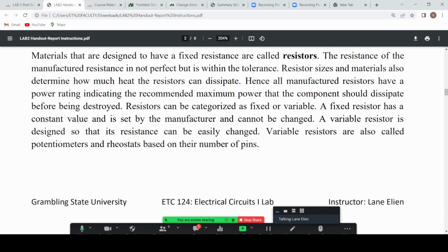That is why we have tolerance, so that we can have quality control. So when we manufacture a resistor, the resistance is accurate to a certain degree, and of course we use the tolerance, sometimes 1%, 5%. So our measured resistance would be anywhere plus or minus 5% or 10% or 1% from the designed resistance.